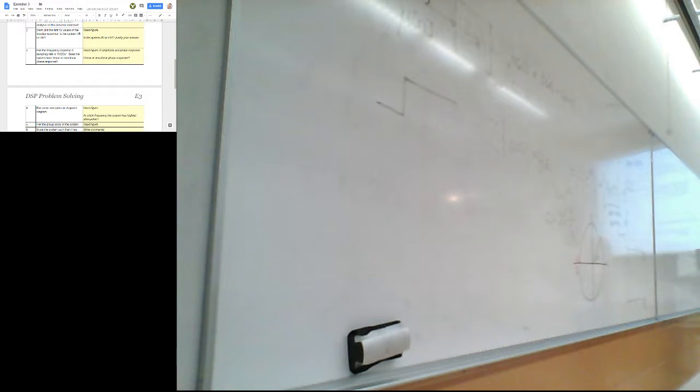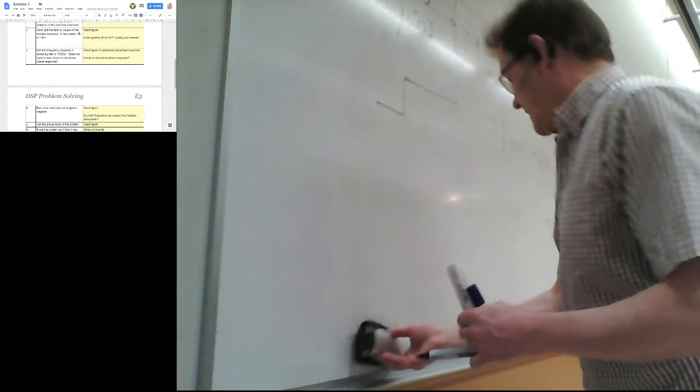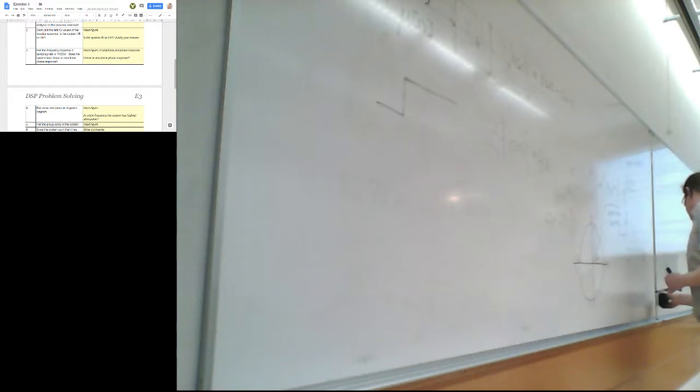And then another graph for the phase response, where basically this part is interesting. The passband is the interesting part, and then the interesting thing there on the phase response is, I drew that one a little bit funny, since usually you don't have advanced phase response, but negative phase response, meaning the signal will be coming after.